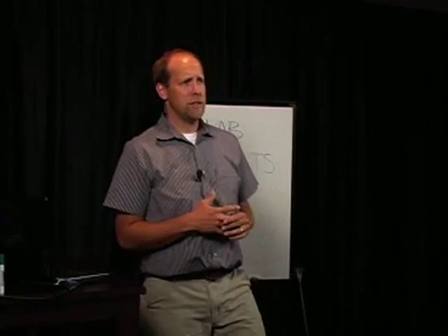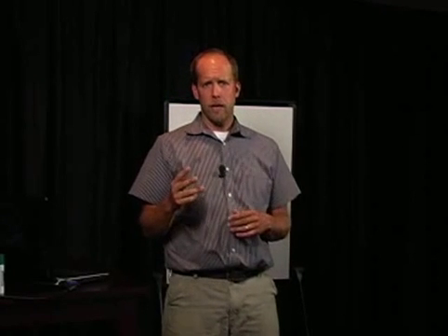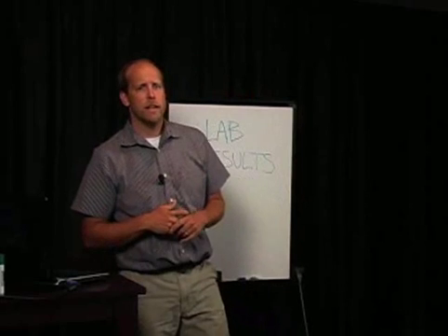Before a remediation project is planned, the size and extent of the mold problem and any continuing moisture problems have to be addressed or measured. Remediation can generally be divided into small, medium, and large. Small being below 10 square feet, medium 10 to 100 square feet. Anything over 100 square feet is large and requires safety professionals and professionals experienced with health and safety and mold exposure and a remediation manager.